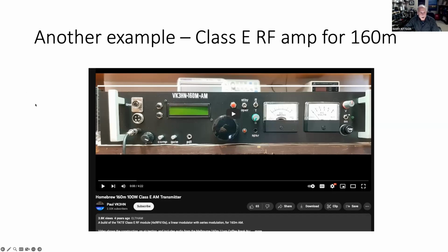All right. So anyway, I just wanted to make an introduction to you guys to these types of amplifiers, because they're not well known, and certainly not well known in the RF community and not in the ham community at all. But if they can be perfected and maybe able to be modulated for single sideband, they might be more and more common in the future. They certainly have made big headways into the audio market at this point. So many amplifiers now that are used in audio applications are Class D and Class E amplifiers.